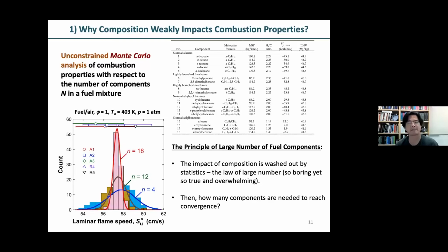Okay. And if I replace n-butylcyclohexane by other large hydrocarbon compounds, whatever this may be, they also crack. They may crack to different types of products, but they always dissociate. And as a matter of fact, if you feed a fuel with larger molecular weight into the flame, I can assure you this flame, from a fundamental flame dynamics point of view, will never be stable because you run into thermal diffusive instability.